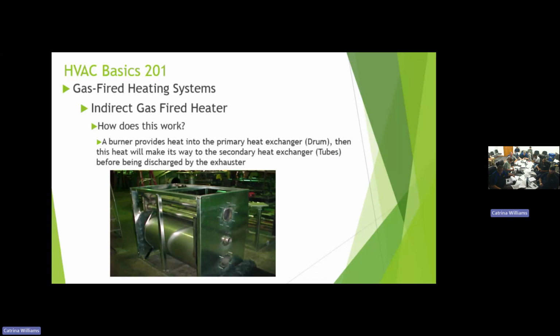So here's a typical picture of one of our smaller chambers. The burner would mount down here and fires into this big chamber. You have what we call two passes in the chamber because the flames shoot all the way down here, almost licking the rear wall, and then it gets pulled back into this collection box on this end.